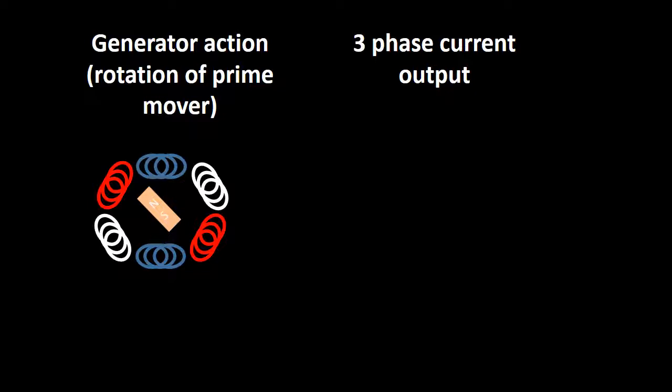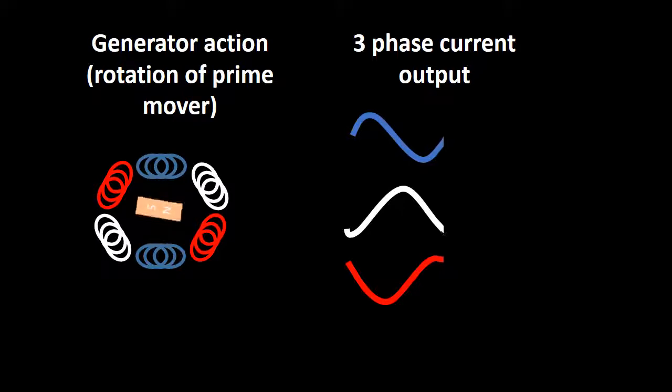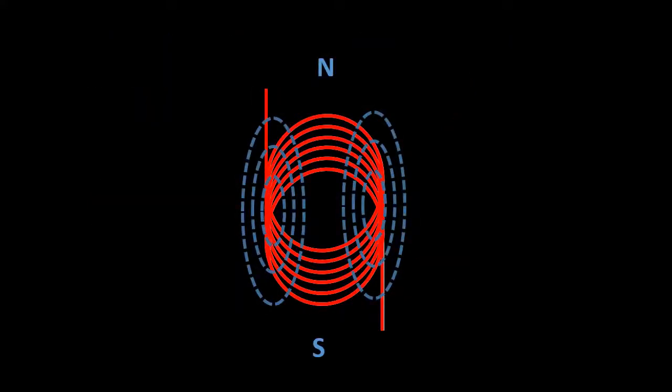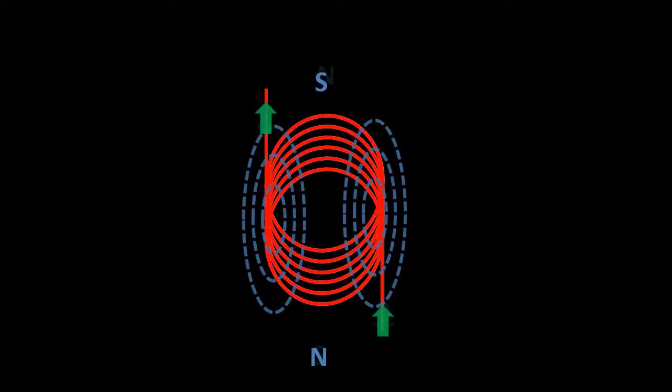This occurs naturally as the output of a three-phase generator. It is also consumed just as naturally by a three-phase motor, as we will see shortly. A magnetic field is created in a coil when a current gets passed through it. It follows that if you feed a coil an alternating current, the resulting magnetic field will also alternate. The frequency of the input current determines the frequency of the resultant field. By controlling the input frequency to a motor, which is essentially just an arrangement of coils, we can control its speed.